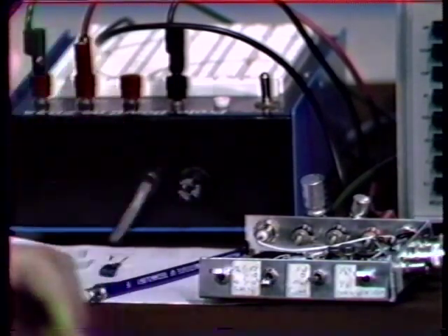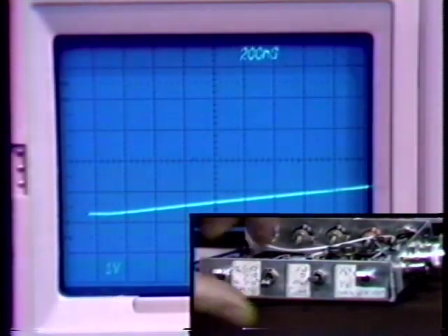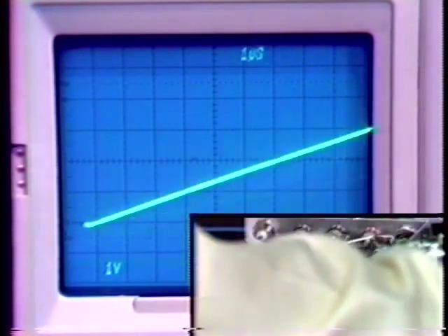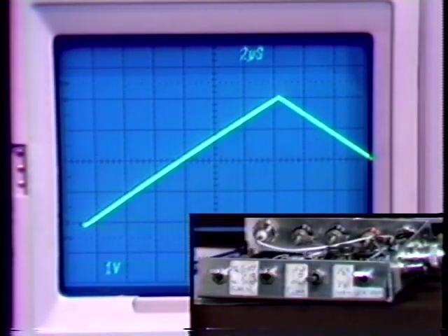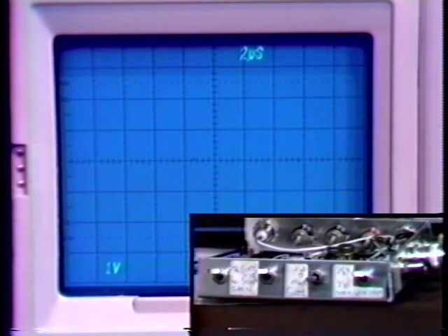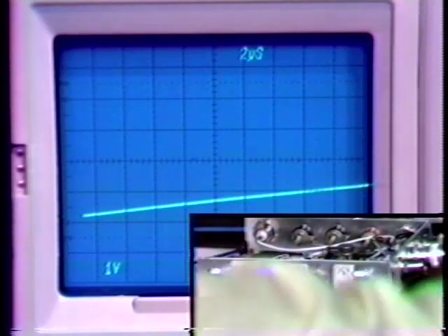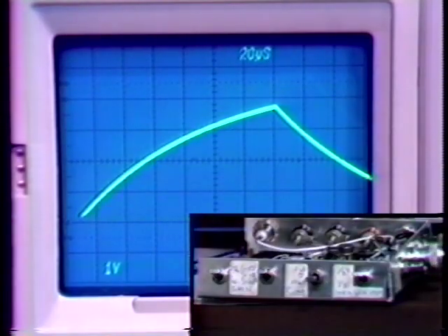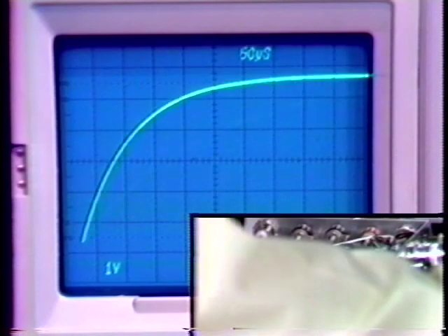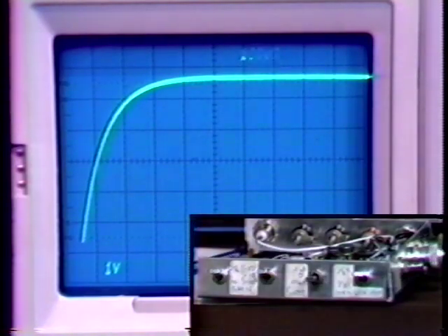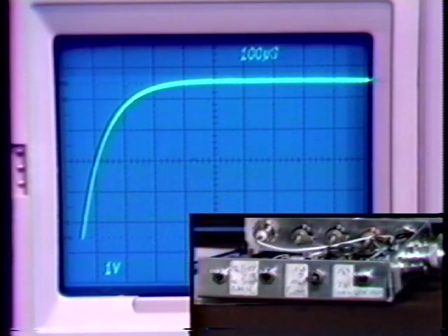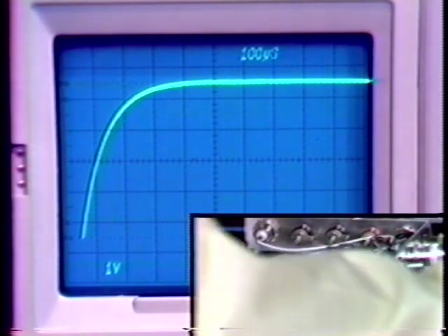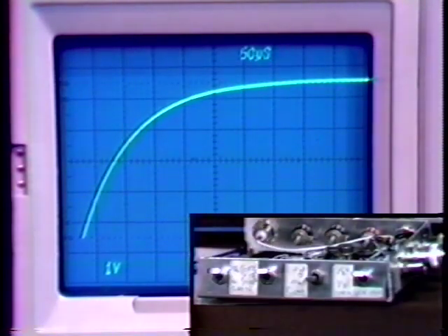And now let's increase the closed loop gain to 1,000. We clearly are going very, very slowly. Let's slow down the generator. Things saturate. We've got to put in a smaller signal. We still haven't reached final value. All right. Now we finally have things adjusted so that we can see the rise time with the 20 picofarad capacitor at a closed loop gain of 1,000.